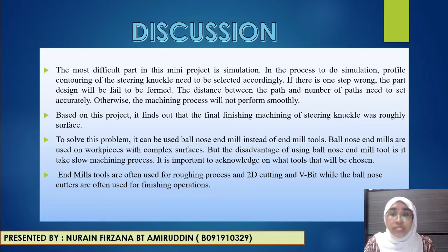In this process, the profile contouring of the steering knuckle needs to be selected accordingly. If there is one step wrong, the part design will fail to be formed. The distance between the pads and the number of pads need to be set accurately. Otherwise, the machining process will not perform smoothly.